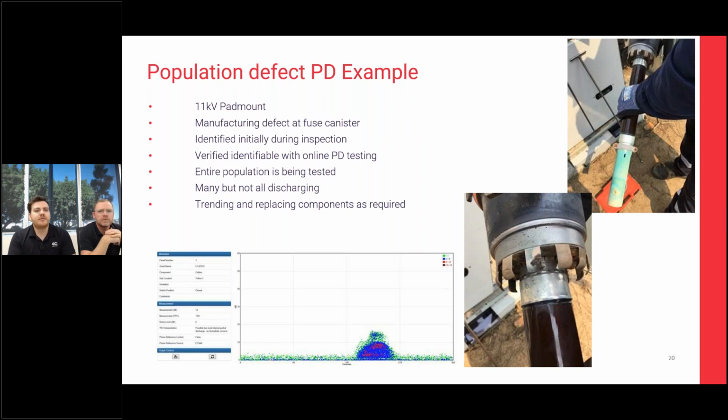This particular problem, they were less worried about the exact defect itself, but the degradation caused by the ozone and the nitric acid buildup causing problems on other parts of the gear, which you can see in the top right image. So this is a problem where it was significantly lower level, but the forensic breakdown that they'd done and the information they gathered during this analysis allowed them to make good decisions, and by finding all of the other ones, they could do the repairs before it necessarily reached this level of degradation, but they had to manage the entire population as a whole.